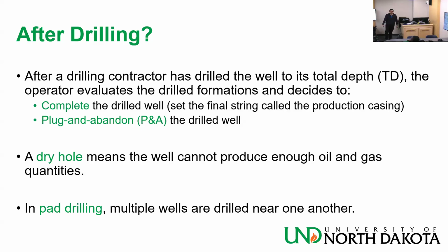But pad drilling means that I'm going to drill 4 wells here and 3 wells there with the same rig. I'm going to drill the lateral where you are sitting, and then I will walk the rig for 12 hours, 10 feet this way, drill another well here, just the lateral, okay?